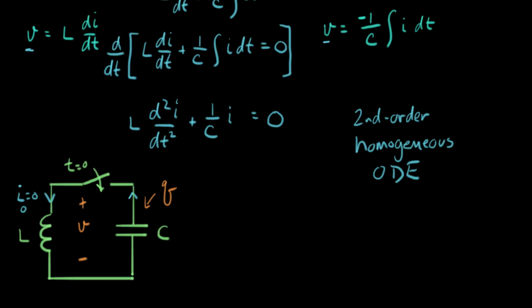In the last video, we set up this differential equation that described an LC circuit, and now we're going to go about solving this second order circuit. The technique that works here is the same that worked with first order ordinary differential equations. We're looking for a function of I that makes this whole equation true. We're going to do that by guessing at an I, putting it back into the equation, and seeing if it works. If it works, we win. If it doesn't work, we have to think of something else, and we keep doing that until we solve it.